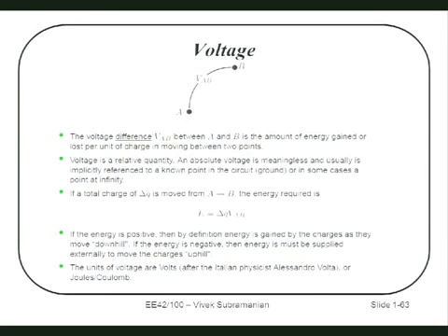Okay, yeah, question? I'm just kind of confused because in the alternating current system, I thought the voltage goes from like 100 to like negative 100. The flow changes. Yes, but the ground stays the same. So his question was, since it's alternating current, since it's going plus and minus, don't your live and neutral sort of flip? No. The potential relative to ground for neutral is always essentially zero. Live will go above or below it. But the ground point reference of neutral should be relatively close to 0. In an ideal world, it's 0.